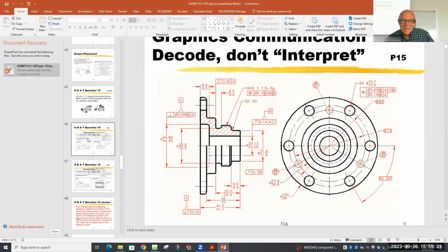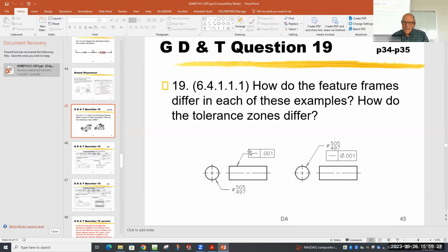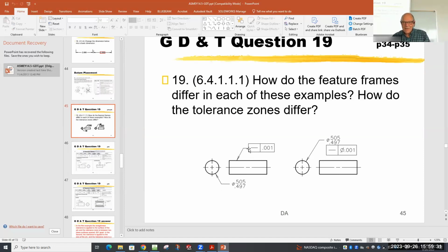And again, I'm not going to try to get you too far into the weeds, but here's a very simple example. That's a pin. So there are two ways to identify the straightness of a pin. That's the straightness tolerance, by the way. And that is as simple as the feature control frame gets. In other words, that pin, say it's this thing right here, it has to be straight because if it's not straight, it's not going to work well. That makes sense to everybody?